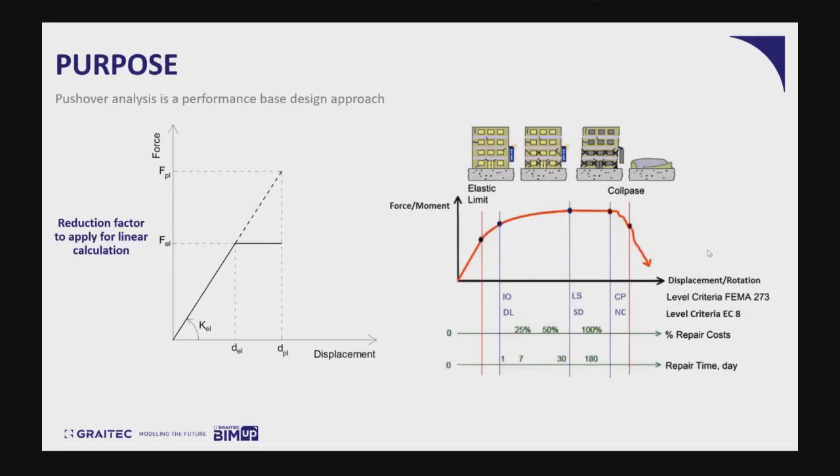Now, pushover analysis is a performance-based design approach. What do we mean by this? Previously, in classical analysis, what we do is a strength-based design. So, previously, we work in the elastic domain. We calculate the internal forces due to earthquake, and then we design the structure according to these internal forces.